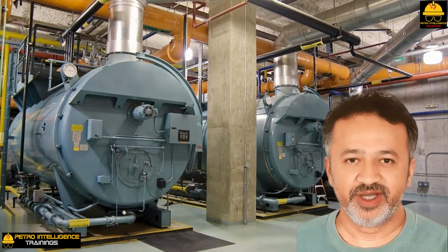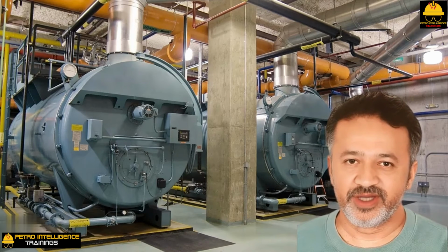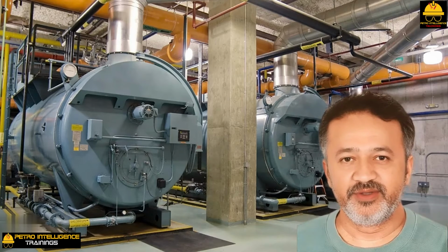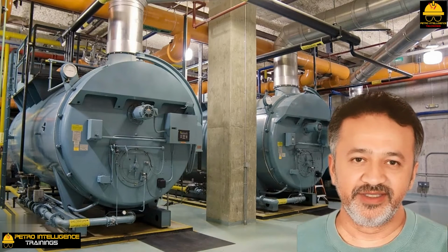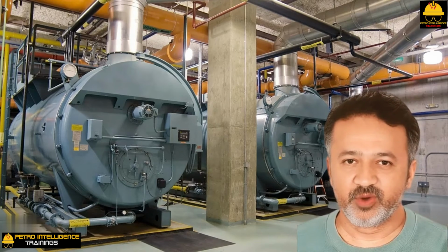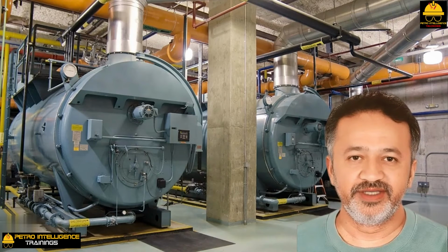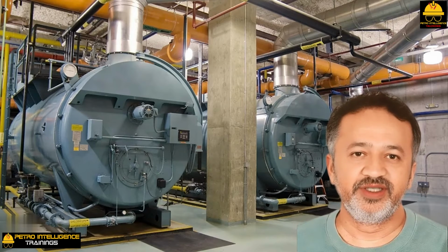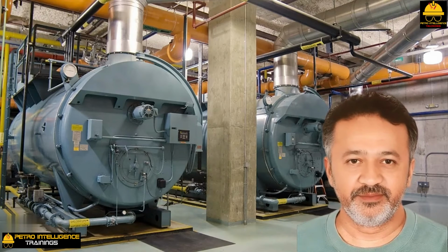Therefore, the temperature increase of the gas oil due to the superheated steam is (650 degrees Fahrenheit minus 450 degrees Fahrenheit) times 2% times 0.5 divided by 0.65, which equals 3 degrees Fahrenheit. The 3 degrees Fahrenheit is hardly worth the investment in the superheat coil.